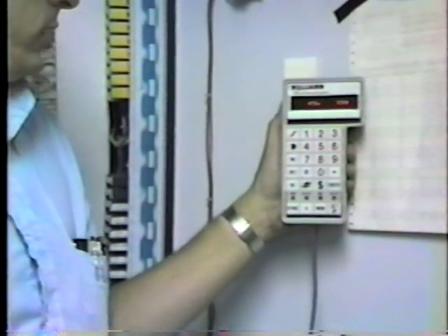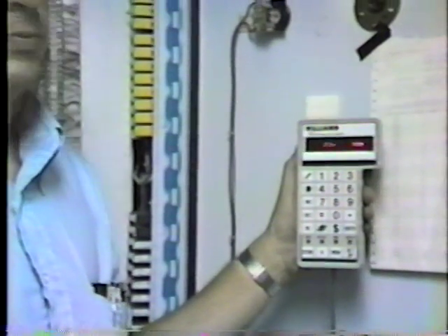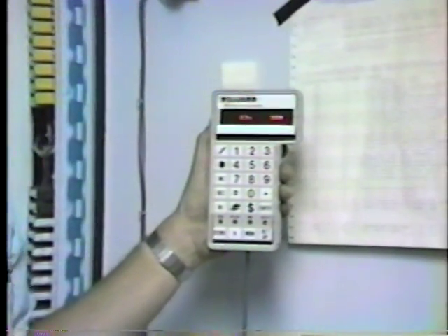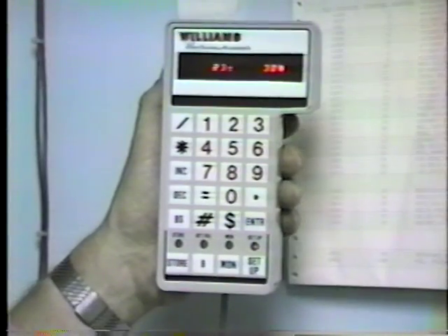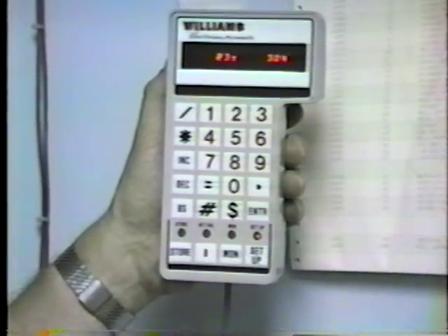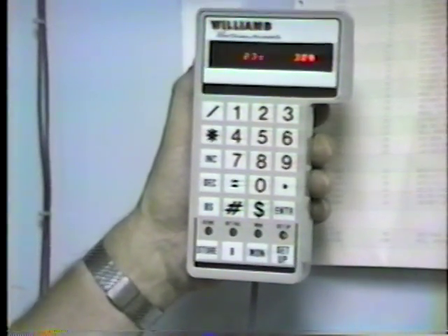All right. 23 is the low delta pressure timeout in minutes. This is the time that we will allow the pulverizer to run at a certain level below target delta pressure before we signal the flame safety computer with an alarm. Correct.